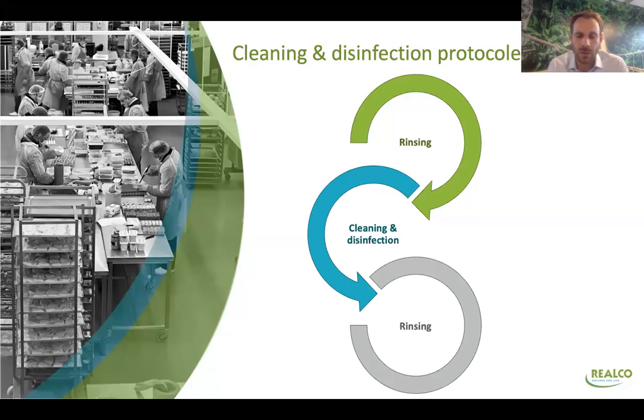You can see also that there is always a rinsing step at the end. The reason is that the cleaning product or even the sanitation product is removing organic matters, inorganic matters, or killing bacteria, and by the rinsing step, you are just removing everything and putting it into the drains. So it's really important to respect that last step, because if you don't, you may have a lot of organic residue that is going to stay on the surfaces. And of course, it's a way for the bacteria that are not killed to eat something and then build resistance with the biofilm.